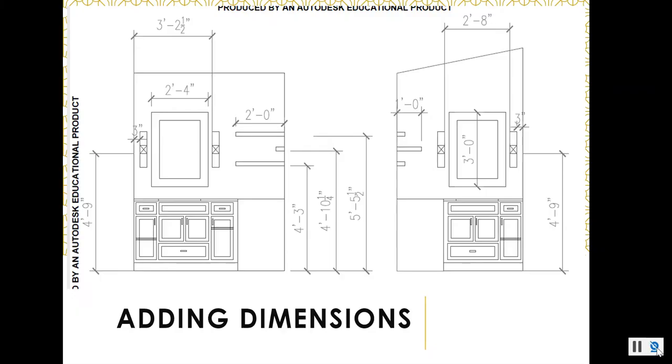Super important. So here they have this floating shelf. They're telling the contractor it's 4 feet 3 inches above finished floor. Here, the other shelf, 4 feet 10 1/4. Here, the third shelf. They're also saying, once again, 2 dimensions. Go over 2 feet. That's your first shelf. And then you have these dimensions. This will tell the contractor how to install the floating shelves.